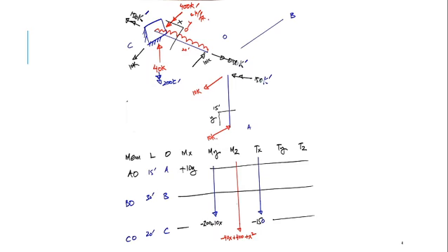This 10 kip is in Z direction and this is in X direction, so there would be a moment in Y. The load is in Z and the member is in X, so there would be a moment in Y. Okay, moving this 10 kip towards C, it forms an anti-clockwise movement.